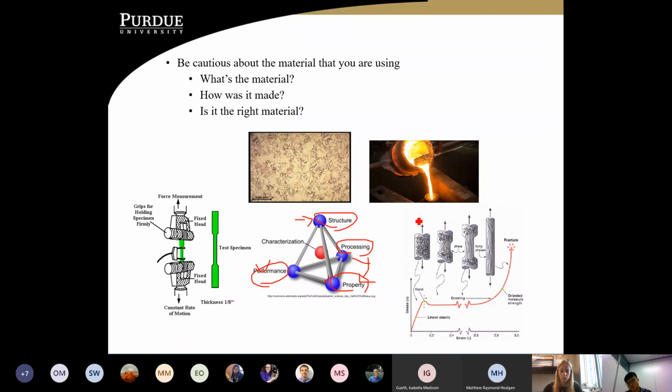What you can do is take these two materials and look at the structure, because I assume these structures are completely different, right? If you zoom in with the microscope, you can see if it was printed at 0, 45, or 90. And therefore you can justify, okay, the one that's higher is because it was printed in this direction, and therefore its processing is different. So we can use the structures to justify that our processing was different. So these three correlations over here are so important.